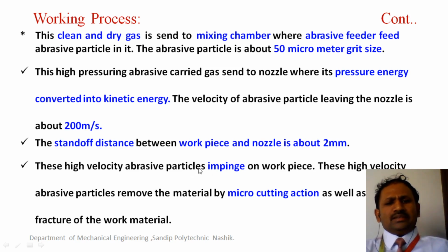Just consider, when that gap is maximum, what happens? The removal of material that should take effect on the workpiece, the cutting size may get tapered or take different shapes. So that's why a standard distance is there. That's why standoff distance, or it is called shortly SOD.